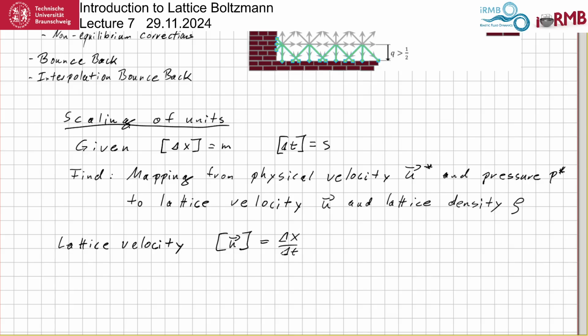So you never use physical units in Lattice Boltzmann. I encourage you not to use physical units in finite elements too, but if you do this in finite elements, at least it will work. In Lattice Boltzmann, it will simply not work. You have to use these lattice units. Velocities must be given in delta x by delta t. Viscosity must be given in delta x squared by delta t. Otherwise it doesn't work. No physical units here.